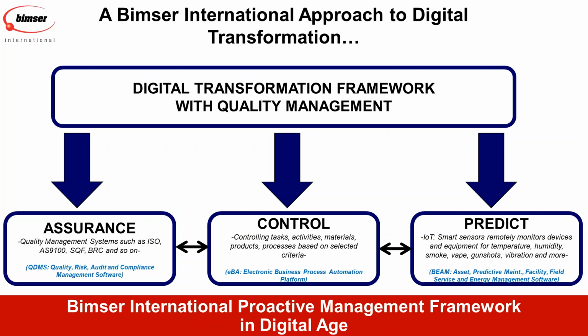Your quality assurance system dictates control, so you need to have control points in your operations. That may be when you are processing the steel, after you process it, or when you receive raw materials from your vendors. Let's keep in mind, quality management is not only about the manufacturing part. We are not only talking about fabricating steel. If you have, let's say, ISO 9001 in place as a quality management system for you to be certified by AISC, for example, ISO 9001 touches every part of your company except finance and accounting.